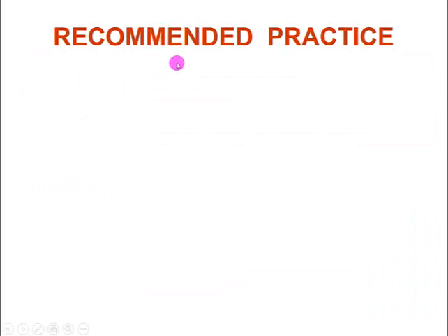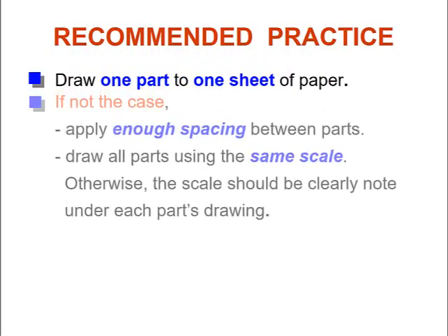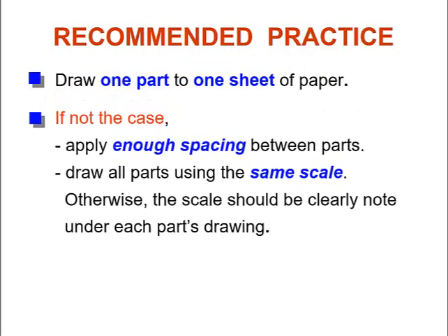So for recommended practice, draw one part on one sheet of paper. Recommended. But sometimes if you have a very small piece or part, maybe you can put more than one part in one sheet. And if not the case, apply enough spacing between parts.